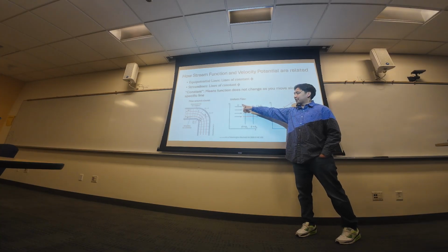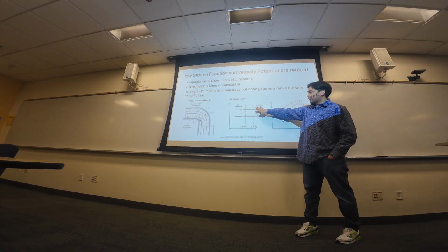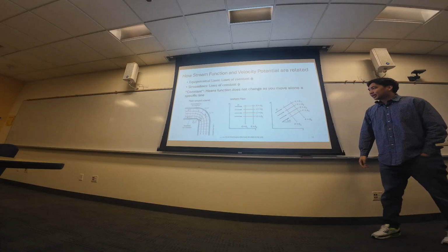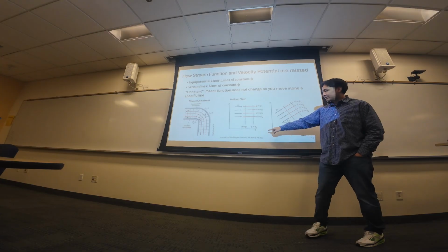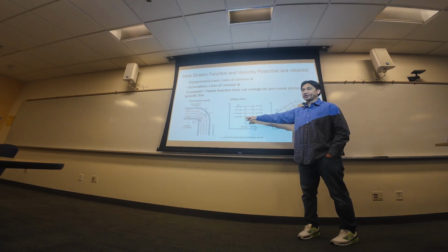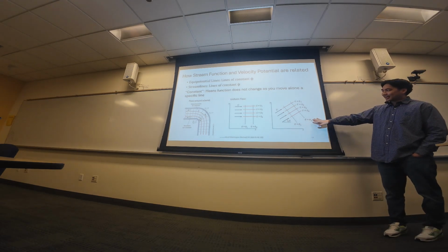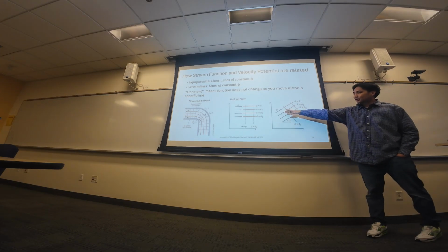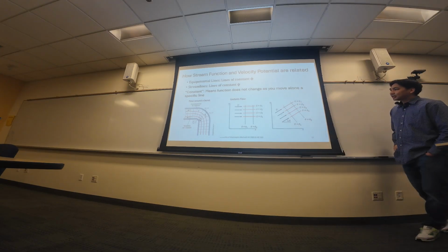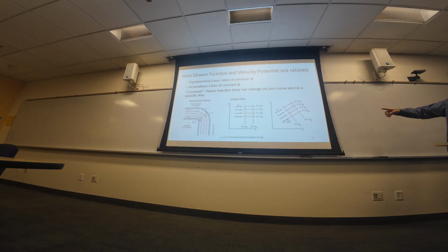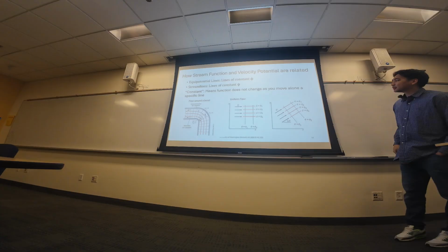We introduced this vector, capital U. It's just your flow in parallel. All your flow vectors are parallel. That's what uniform flow means. And you can see these are your psis, 1, 2, 3. These are your phis, 1, 2. They're just perpendicular to each other. So here's another, even more repetitive. If it's at an angle, these are your velocity vectors, capital U. So psi is going in the U direction. And then your phi, your velocity potential, is perpendicular to that.